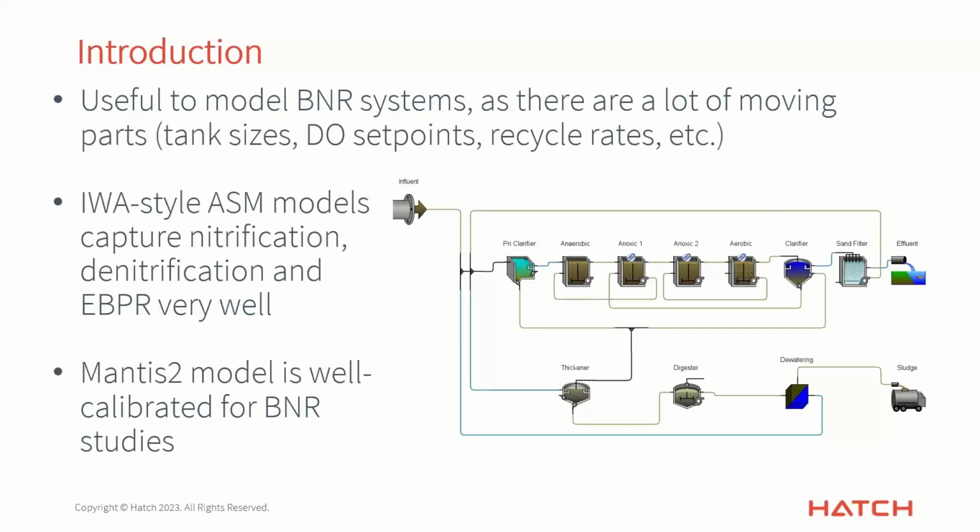The good part about all of this is the IWA style ASM models that you see in GPSX, which were based upon that ASM1, ASM2d type of approach from 30 years ago. They capture nitrification, denitrification, and EBPR or BioP processes really well.